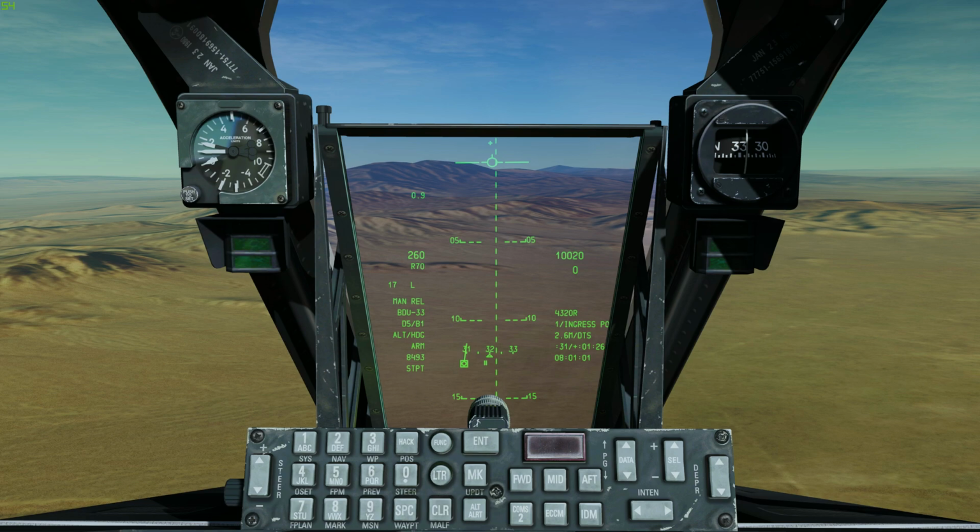The zero sight line is a reference line extending along the longitudinal axis of the aircraft. All sight depressions are referenced to the ZSL. We will use the depressible pipper as a reference to the aim-off point. The depressible pipper can be manually depressed over a range of +10 to -300 mils, referenced to the zero sight line. To set the depressible pipper to -34, press the depression rocker switch.